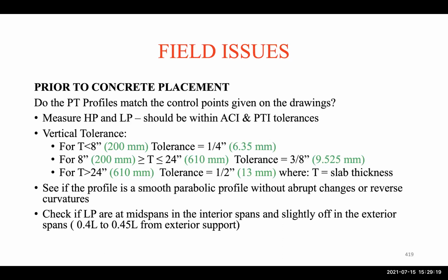We put in the drawing how much from the top, how much from the bottom. So do they match? That has to be checked. So we need to measure the high point and low point, and those are given and should be within the SEI and PTI tolerances, and these tolerances are given here, for different thicknesses of the slab. See if the profile is a smooth parabolic profile without abrupt changes or